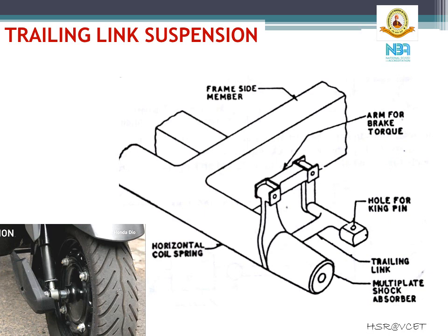A torsion bar has also been used in certain designs in place of coil spring. This system does maintain the camber and the wheel track constant. However, the distance between the front and the rear wheels does change. Difficulty to remedy this defect is the main reason for its very limited use in actual practice.